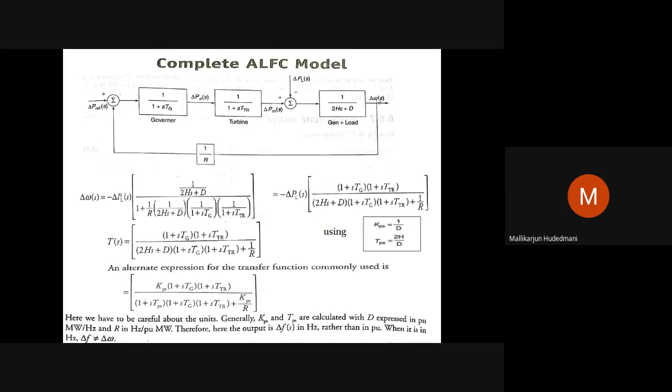So this frequency error deviation is fed back to the input block here in this first governor block. How does the governor adjust it? Governor will take a request from the reference set point. If the reference set point, which is set originally, makes the requirement of these things fulfilled, then this delta omega must be 0. Delta omega is 0 means what? Error is 0. The frequency appearing is the actual required frequency, and it must be meeting the loads perfectly.